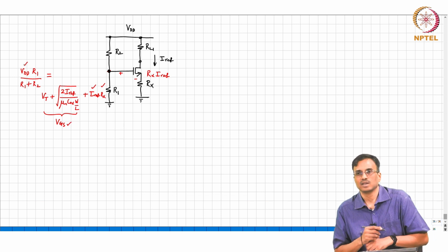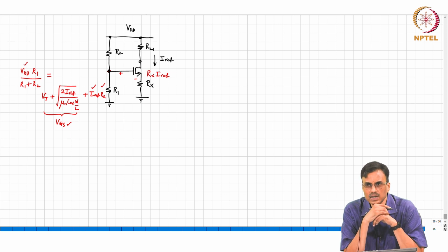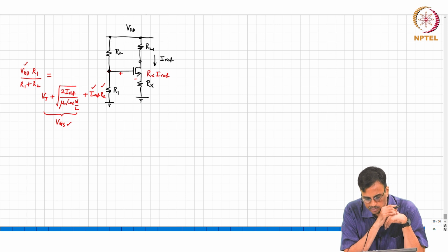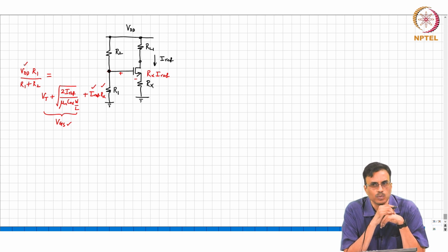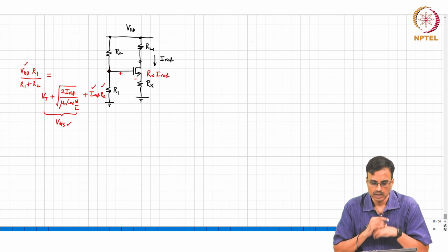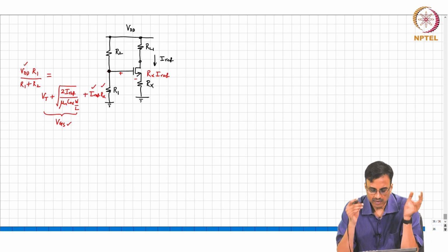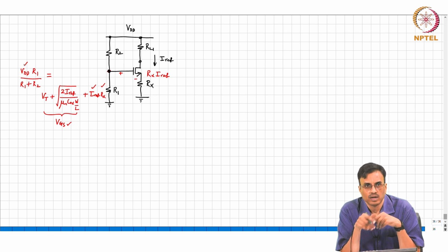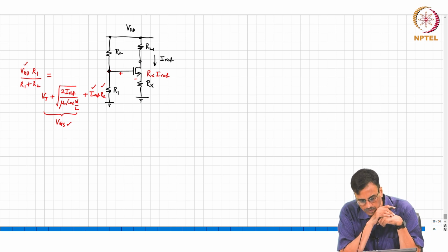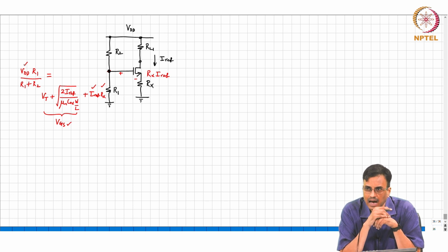From this you can find the ratio between R1 and R2, and as usual we will choose the parallel combination of R1 and R2 to be much larger than Rs. Now, staring at this picture, how do we convince ourselves that Rx actually helps in stabilizing the bias current?